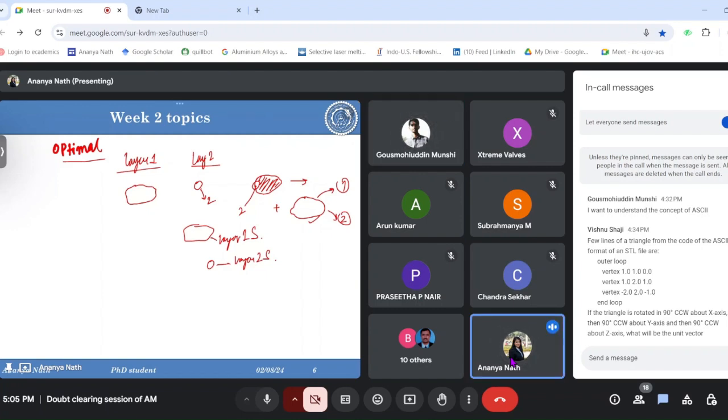And then comes the next portion, which is some terminology related to the support. For this part, it looks like this portion is empty, but this is connected to the base like this. So obviously for this part, no support is required because there is no overhang portion. But for this part, support is required.